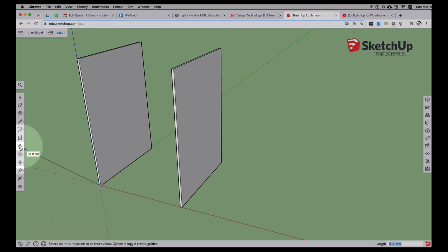Perfect. Now let's put in some shelves. I'm going to draw the shelves up on the side, just like we did with that third stair. And this is going to be 50 by 1. I'm just typing that in. And then we need to pull that out. And notice as soon as I got close to that edge, it snapped it to that face. I could keep going, but that's not really what we want.